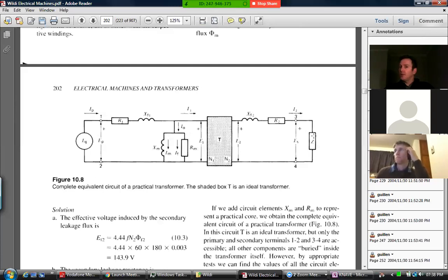This is the load. It's not the transformer. This is outside the transformer. That's the resistor or whatever impedance you put there, that you've got choice of what you put there. This is all in the black box inside the transformer. You can't see it. But we'll take the load as well, times A squared, move it to this side.